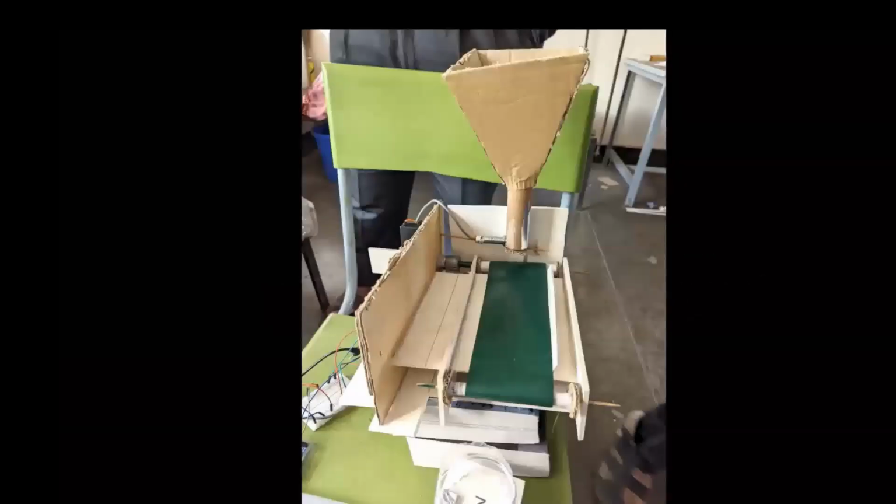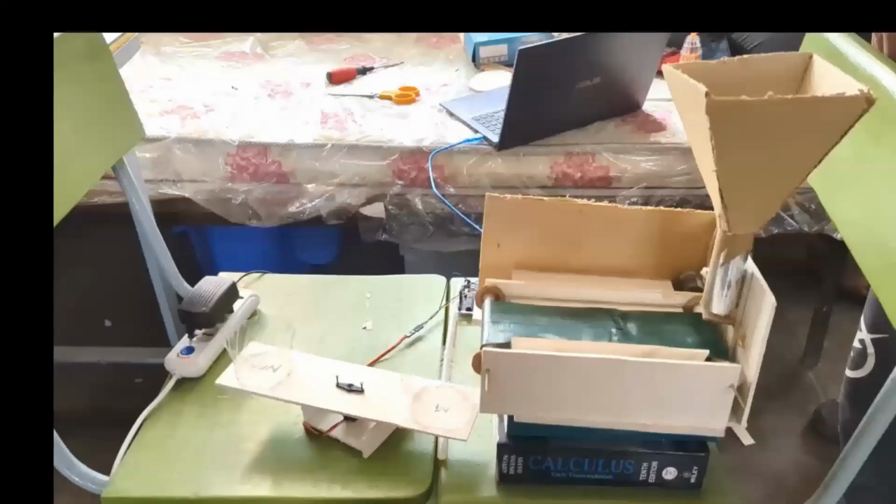Now we will move on to the sorting part, which is very important in our project. Here is the structure of our sorter as we previously saw in our slides. The capacitive sensor is lying below the valve, which is our main processing unit. It can detect metal and hence sends a signal directly to Arduino. The valve controls the movement of garbages one at a time. The holder above contains all the garbages together.